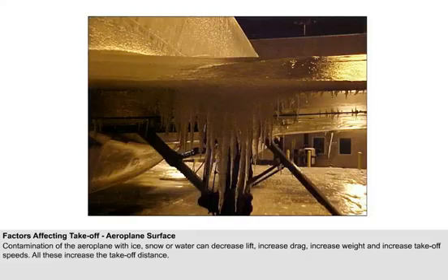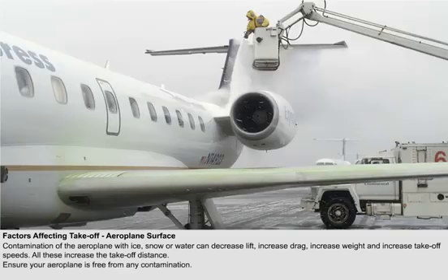Icing conditions can also lead to the jamming of the control surfaces and blockage of important instruments. So it is vital that a proper pre-flight inspection be carried out, and then subsequently the correct method of ice removal is carried out. It is compulsory by law to ensure that all aeroplanes are free from ice and free from any contamination at the commencement of takeoff.